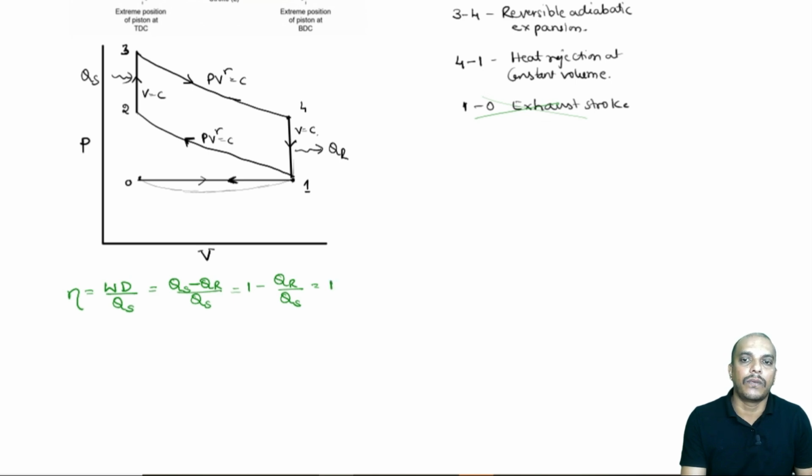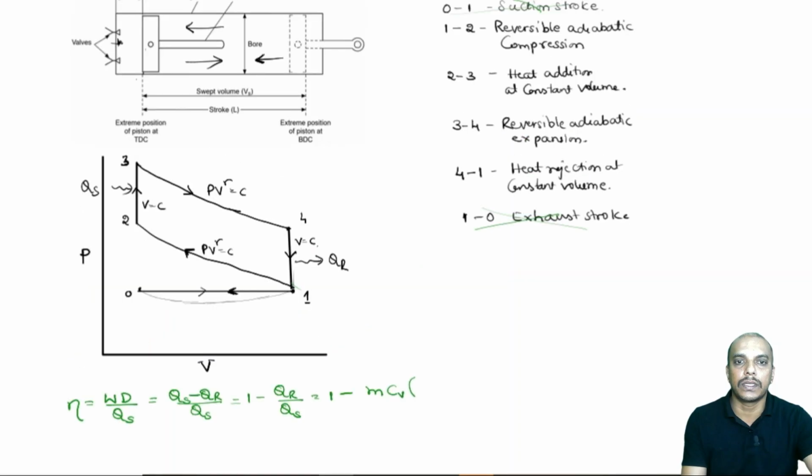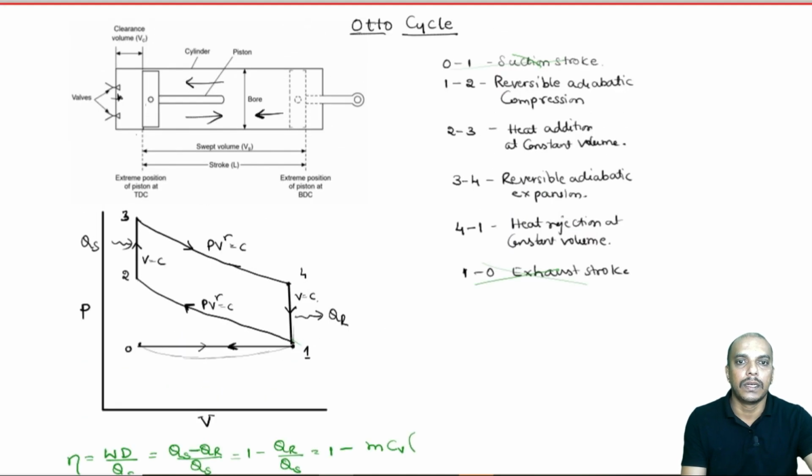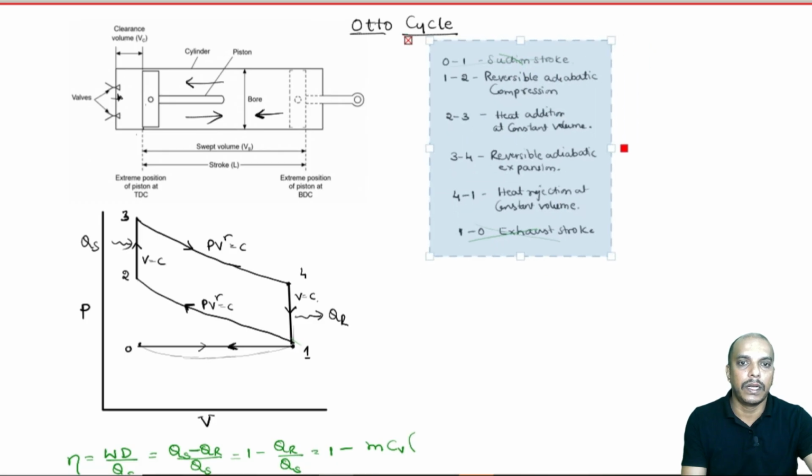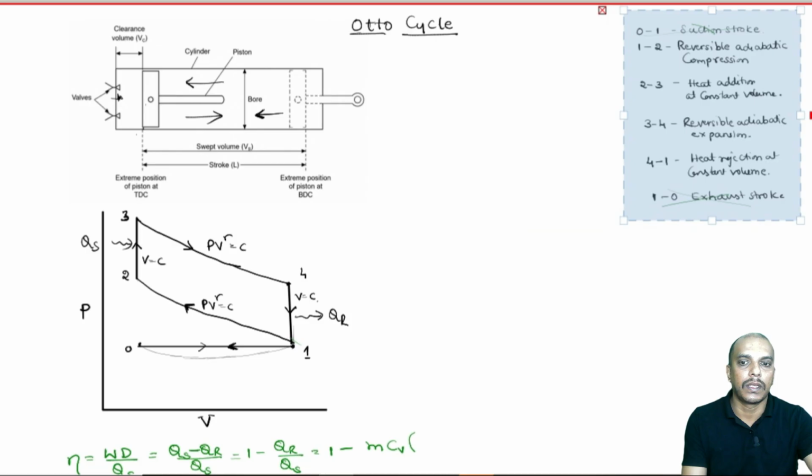Now, for constant volume, which we have already discussed in the last class, heat transfer is given by mCV dT, all right. Heat transfer is mCV dT. So, heat rejection is mCV, heat rejection is happening between 4 and 1, and to keep it positive, all you have to do is highest minus lowest. Now, temperature versus entropy diagram also we should have drawn, because temperature is what we can estimate here. Okay. So, let us try to write the TS diagram here, TS diagram for the same cycle.